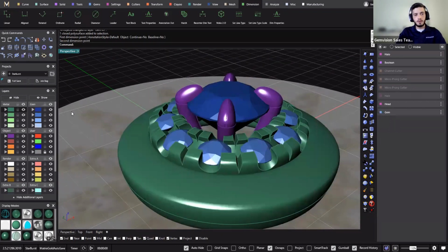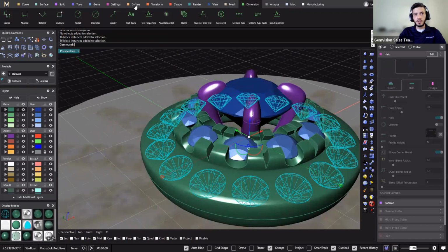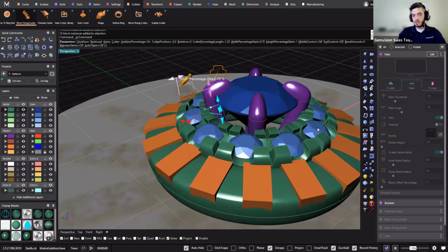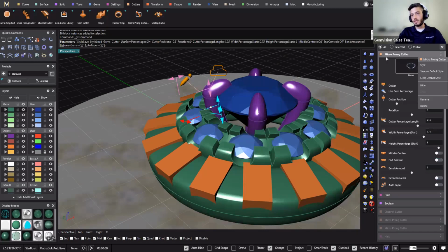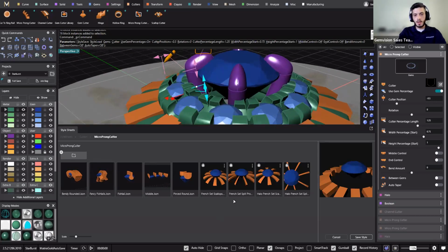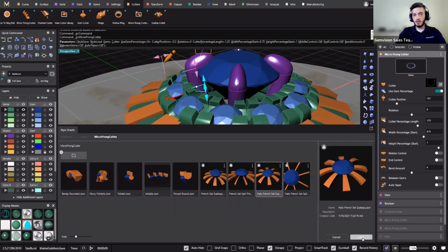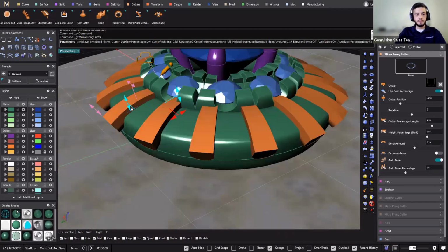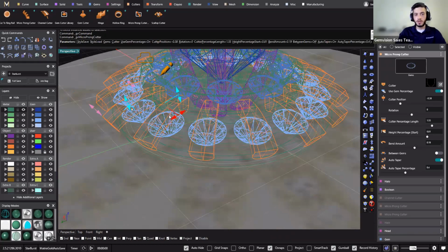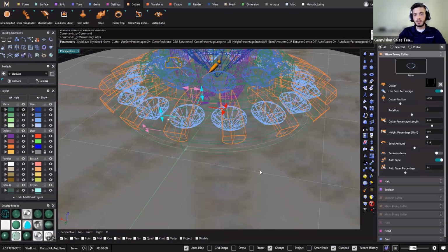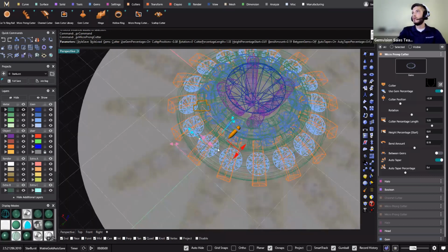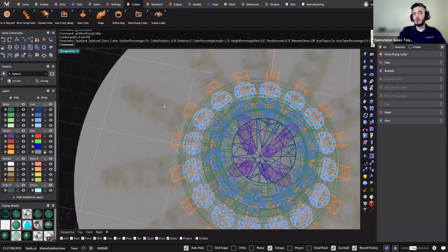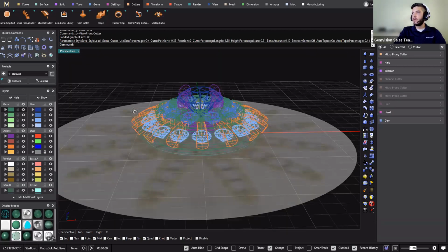All right. So I want to select my stones. Again, we can go to cutters, do micro prong cuts. So because we already saved our style, right, we can go to styles. And we can choose Halo French set scallops. If I go here, we can check the width. It should be 40%. It is. I can press enter. I'm at the V point.